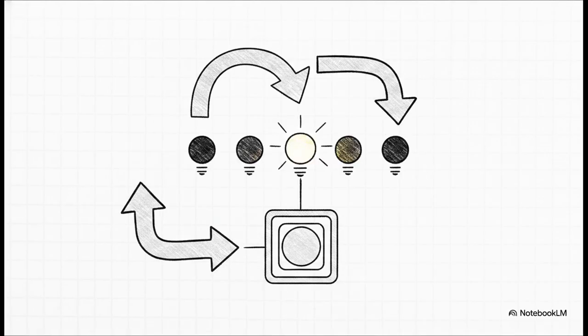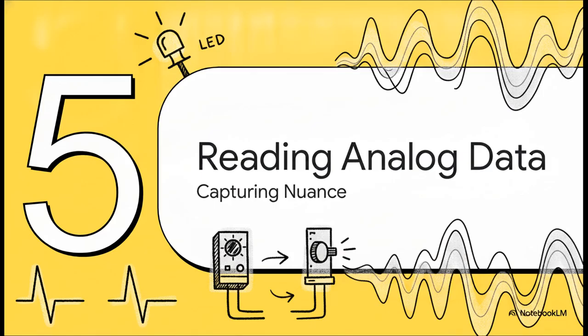Once you've got that basic blink down, a whole new world of physical control opens up. You can start combining the if statements we reviewed earlier with real hardware inputs to create pretty complex patterns. Just imagine reading a 1 from a physical button on port B and using an if-else structure to reverse the direction of a sequential LED light show. At that point, you are literally commanding physical electricity using pure software logic. It's a great feeling.